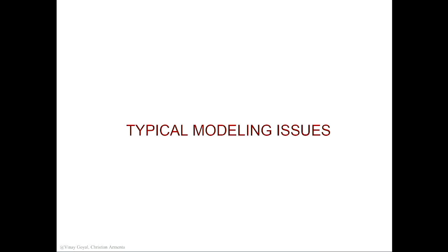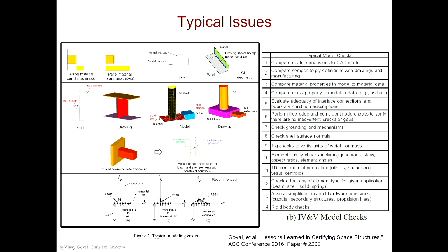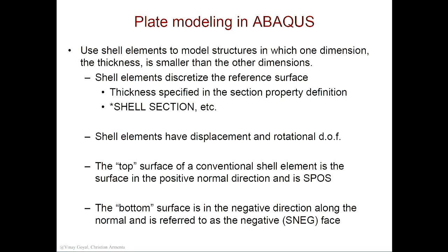Okay. Typical modeling issues. I'll come back to this next week. Abaqus applications. Let's talk about Abaqus applications. So you can use shell elements to model structures in which the thickness is smaller than the other dimensions. The star shell section allows you to implement those.